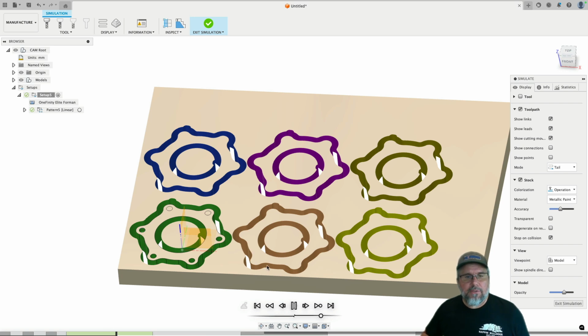Now I could have set this to complete one part with both the two tools on each part before moving on to the next, but it's just more efficient to do it one tool at a time across all parts. So that's the way this was. This is, to me, a big efficiency. This is a nice time saver in a shop. Fewer setups, fewer tool changes, less time to machine, and a very easy thing to do.